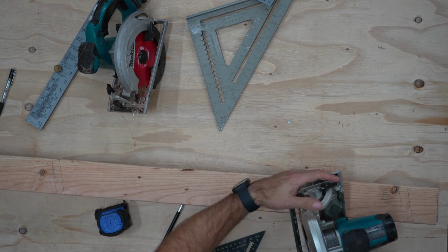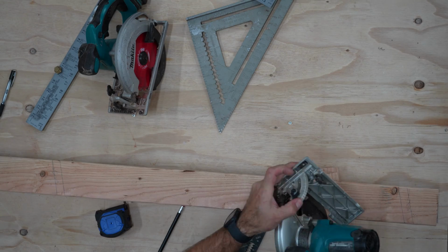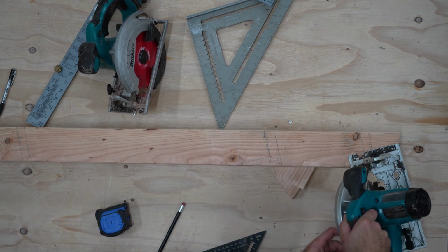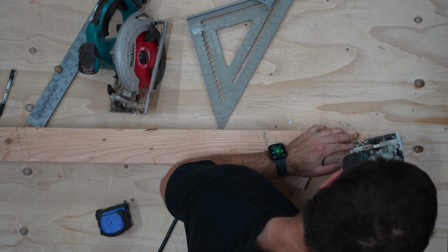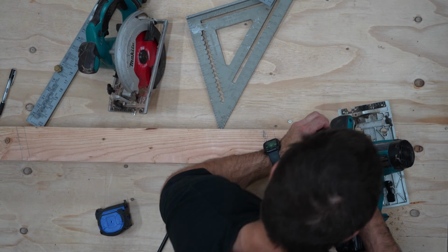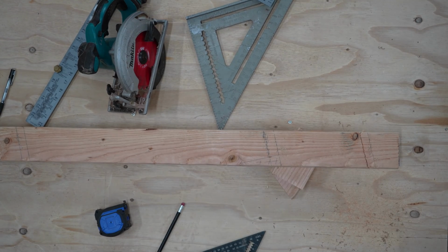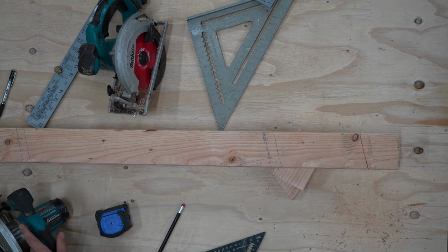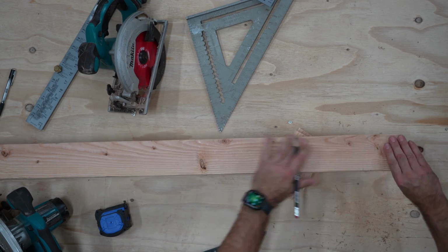Once everything is ready to cut, I like to have two saws so that I can always have one set to 45 degrees. That way I don't need to switch back and forth. But one saw works fine. You would just need to switch between 45 degrees and 90 degrees in between cuts. The next common mistake is to cut the 45-degree angle from the wrong side.